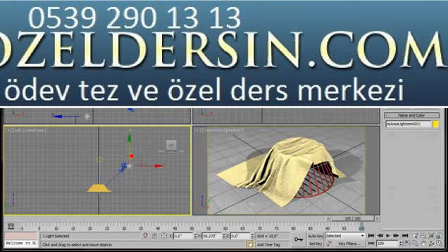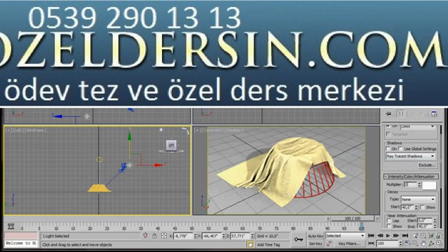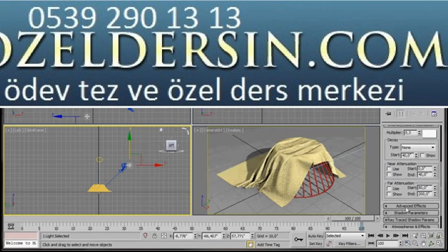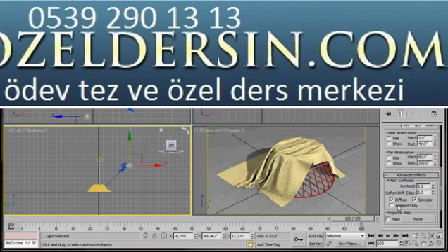We'll come over to the Modify panel. We're going to turn off Shadows. And in Intensity, we're going to bring the multiplier down to 0.3. Now we'll go to Advanced Effects and we're going to turn off Specular. We're going to create one more light.